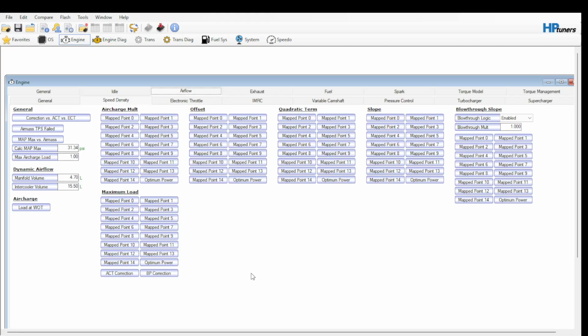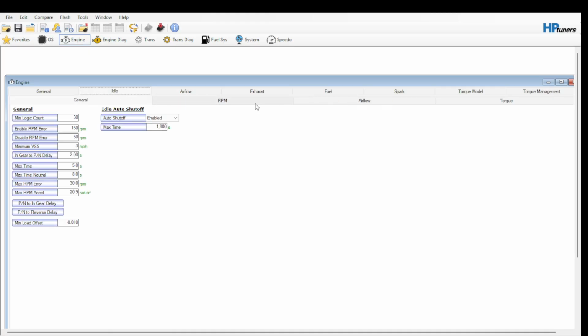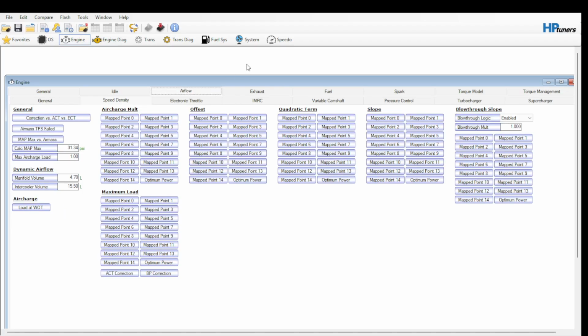Now, they activate at certain load. So if you're driving, occasionally if you let off the throttle rather suddenly, or you're just at a stop. I think in idle controls, actually, yeah, if you go to idle right here, it's VSS speed. I think stock is 2 miles per hour, and I changed it to 3. Don't question me. I'm highly specific with what I want out of my tunes, and still they work most of the time. And that's a joke.